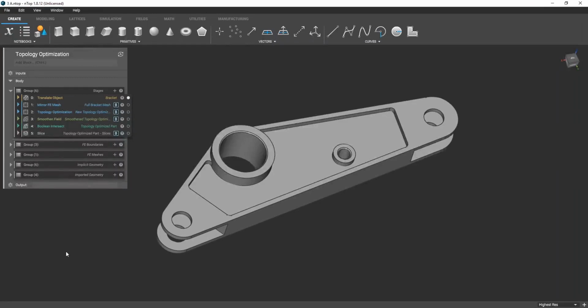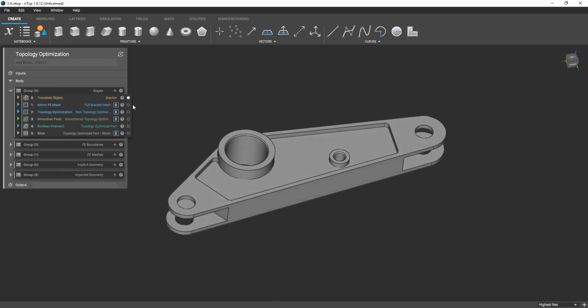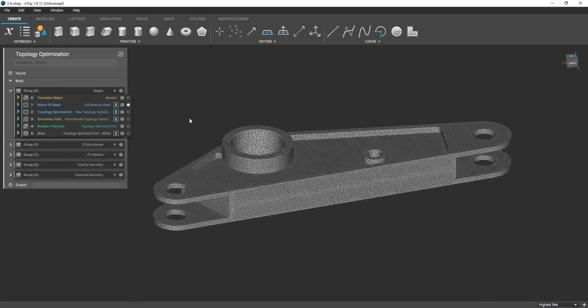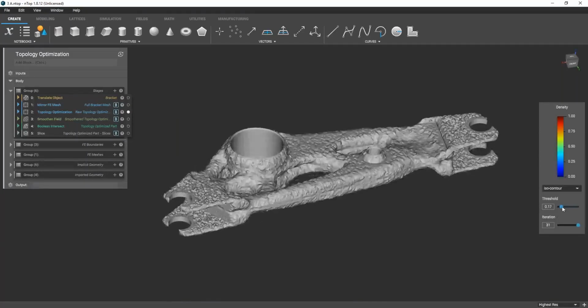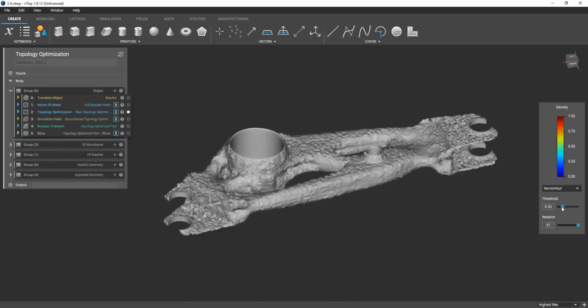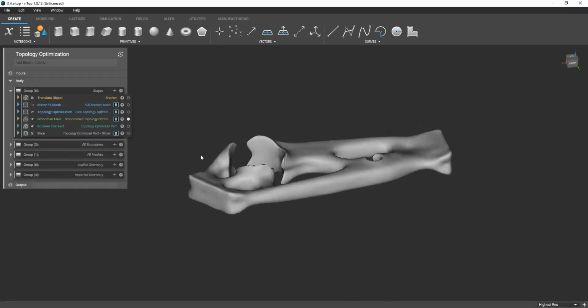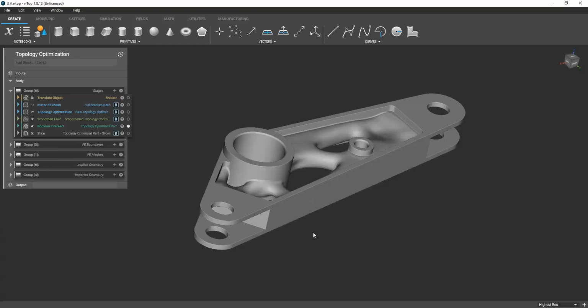Now, this topology optimization workflow here is quite comprehensive. The initial imported step file is up here, and not only can we accept step and parasolids, but we can also take native SolidWorks or CATIA files and bring them into our modeling environment. From there, we convert to a volumetric mesh, perform an optimization, pan through the threshold to assess what looks best, and then perform a quick and thorough smoothing operation. Finally, we can rejoin it with the critical connection geometry to finalize your optimized part.